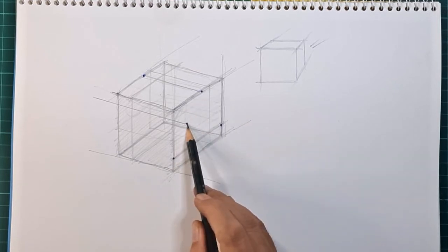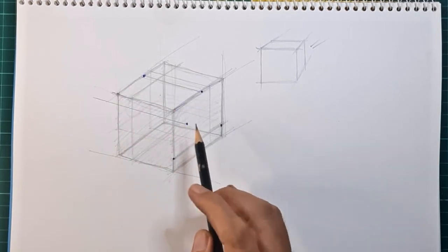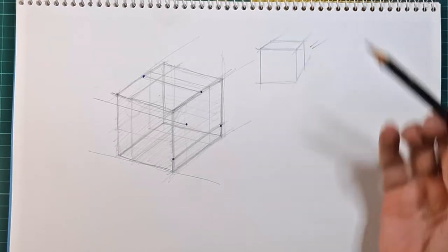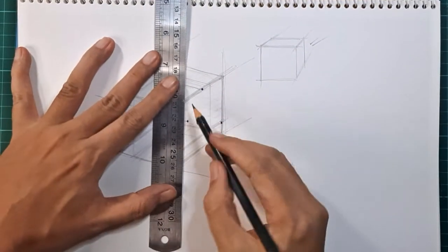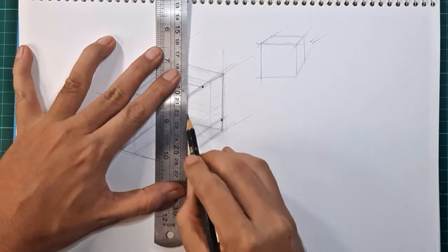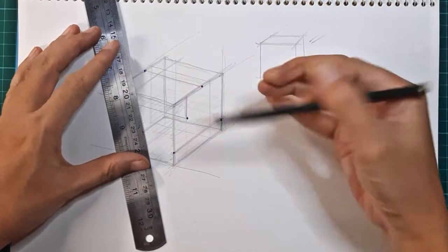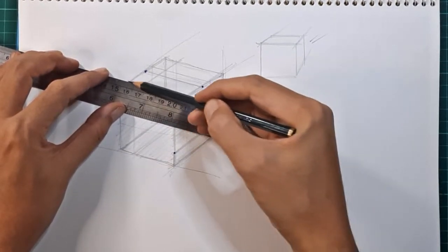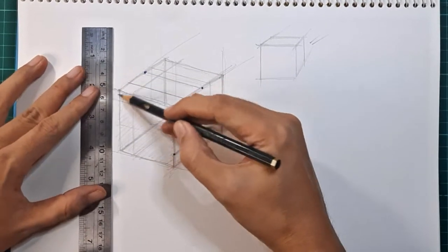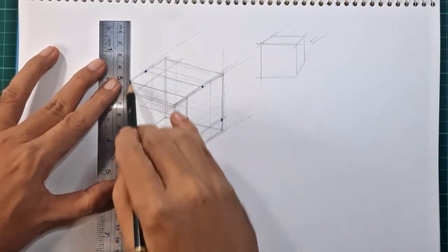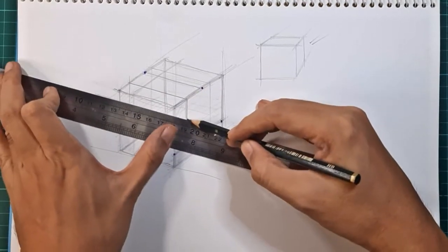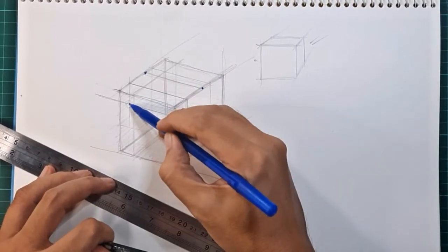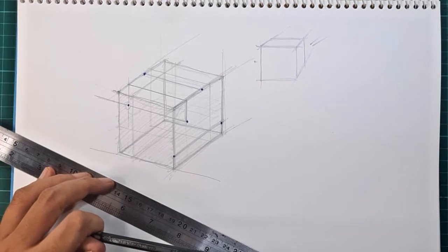We can use contour lines that go around the volume. What does that mean? This vertex sits on this face. So what I'm going to do is project a line going up, continue that line over the top, and go down along this face, parallel lines. Since I've already established this parallel line over here, this intersection is exactly where that vertex will be on the other side.